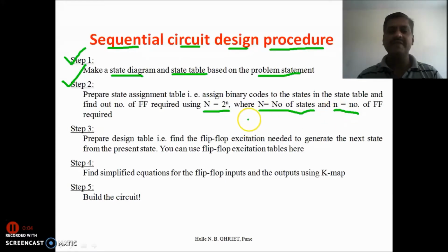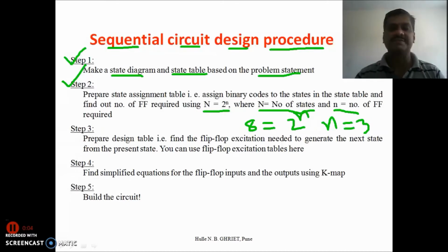Means here, if we have 8 states, then 8 equals 2 raised to the power of n, and if we find the value of n, it will be 3. So in this particular case, 3 flip-flops are required for this design.